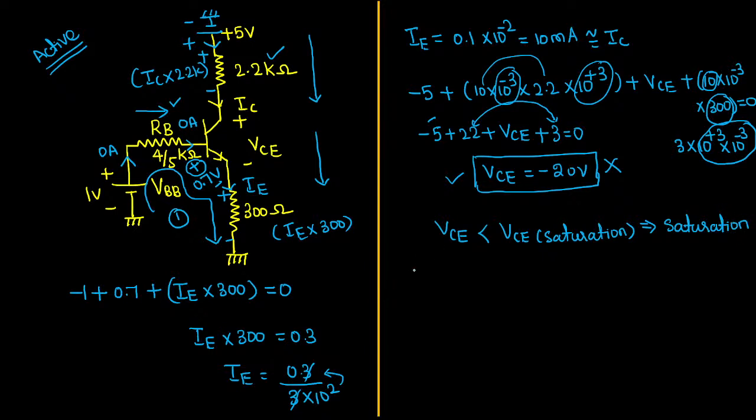Okay, sir. If the transistor is in saturation region, then we know the value of collector to emitter voltage is fixed. That will be 0.2 voltage. We know this value in the saturation region. So you can write the value of collector to emitter voltage is 0.2 voltage. First conclusion. Again start the operation from the beginning. Take the same circuit. Remaining all are correct, but you have to reanalyze, and once again we have to calculate the value of collector current.